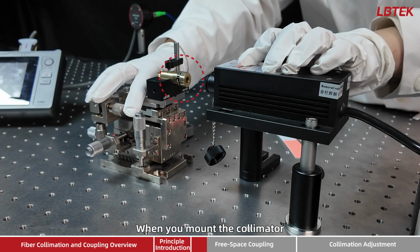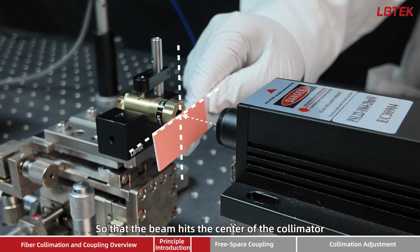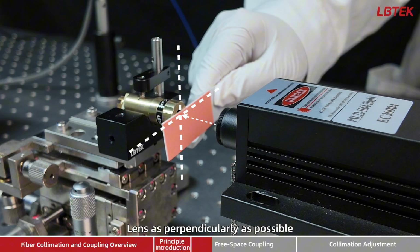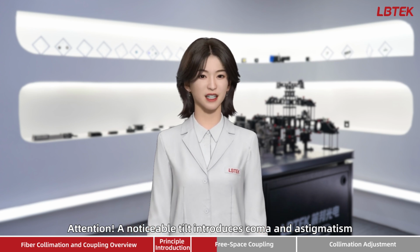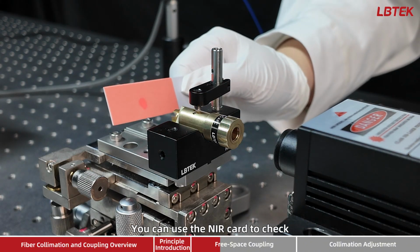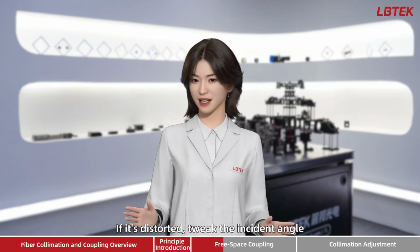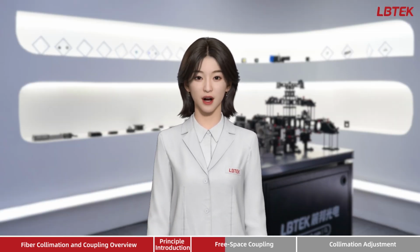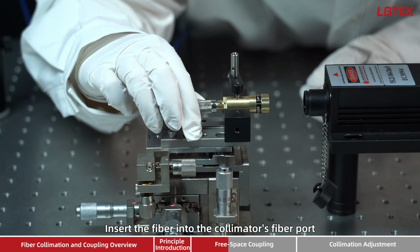When you mount the collimator, adjust the coupler and the free space beam, so that the beam hits the center of the collimator lens as perpendicularly as possible. Attention! A noticeable tilt introduces coma and astigmatism, which hurt coupling efficiency. You can use the NIR card to check if the spot from the fiber end is circular. If it's distorted, tweak the incident angle. When the spot is circular, insert the fiber into the collimator's fiber port.